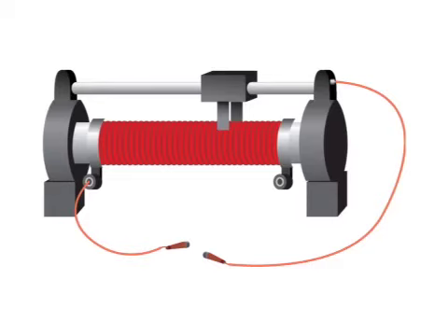So this kind of variable resistor is used in volume buttons for radios and televisions and whatever else, or it used to be anyway. I think there's a lot more electronic now, but this is the idea. So as you move the slide down here, it's less resistance, more electricity goes through, and the volume becomes louder. As you move the slider further up here, it's got more coil to go through, therefore it's more resistance, there's less electricity to get through, and the volume is softer.